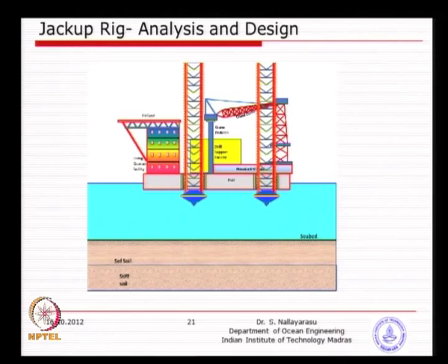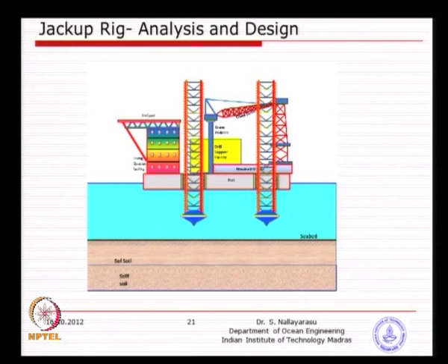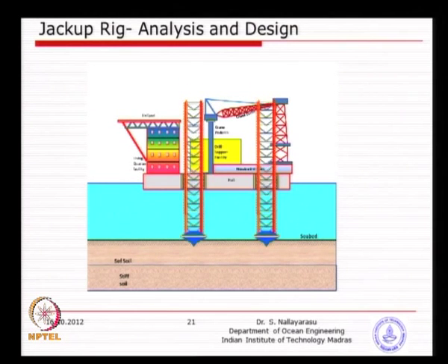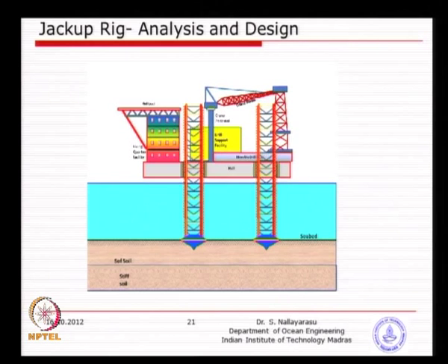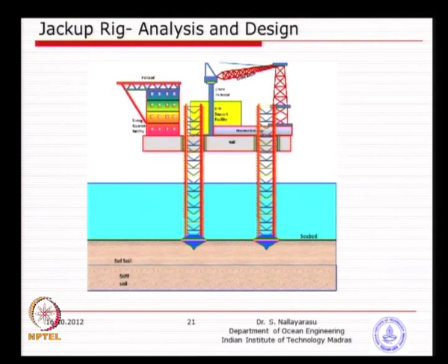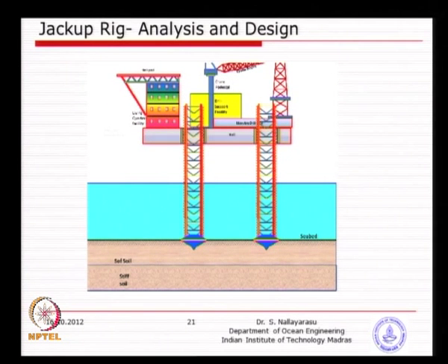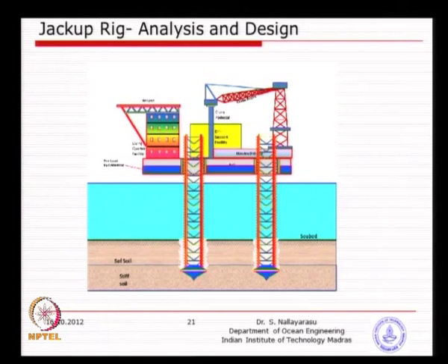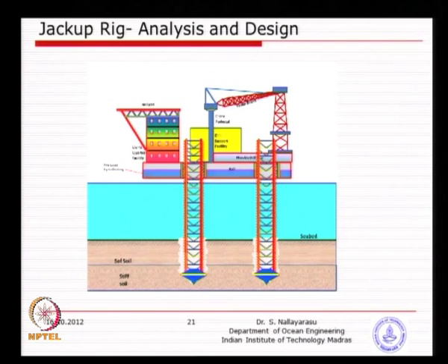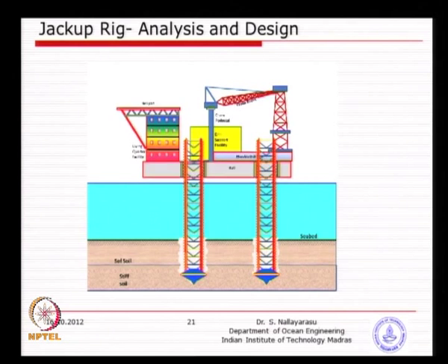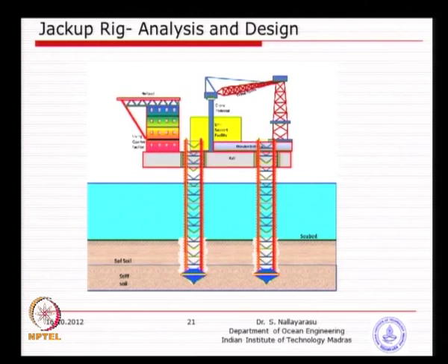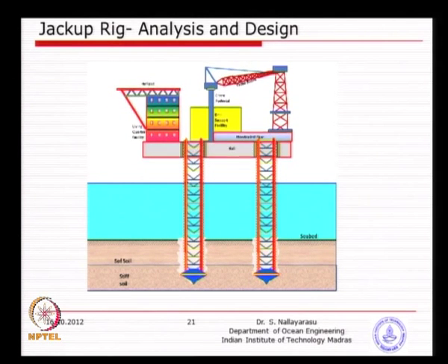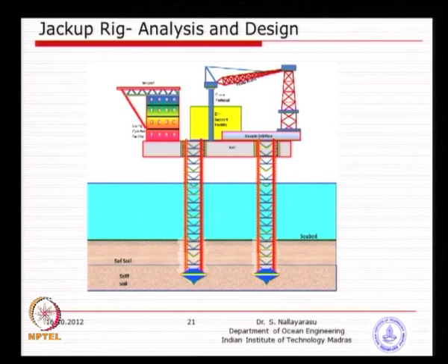We will see just a quick animation of how it happens. Carefully watch. Basically this is the stage. You have to be very careful before raising, because at that stage the hull was still floating, and then the ballasting is happening. Once it is ballasted, then it is trying to penetrate by displacing the soil onto the side, completely. You have no control over it, and then you raise the hull to the higher elevation. So, this is the sequential operation.